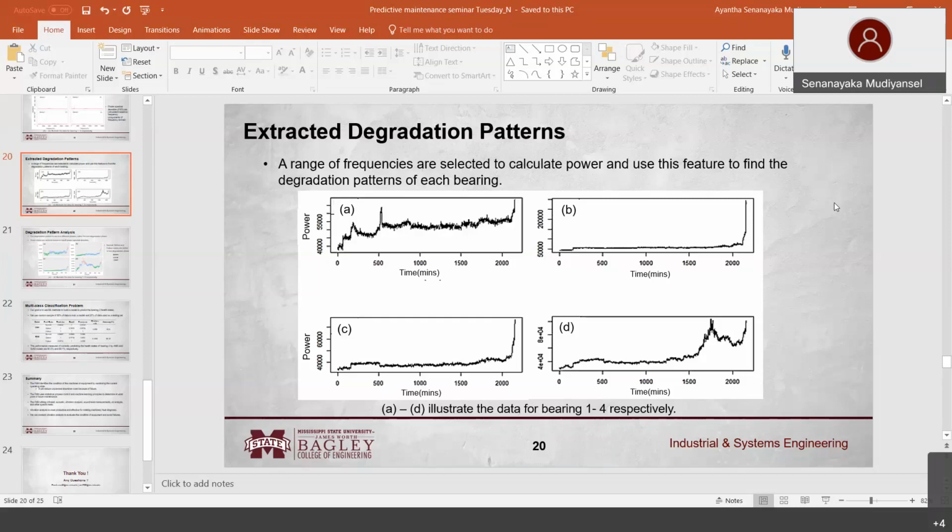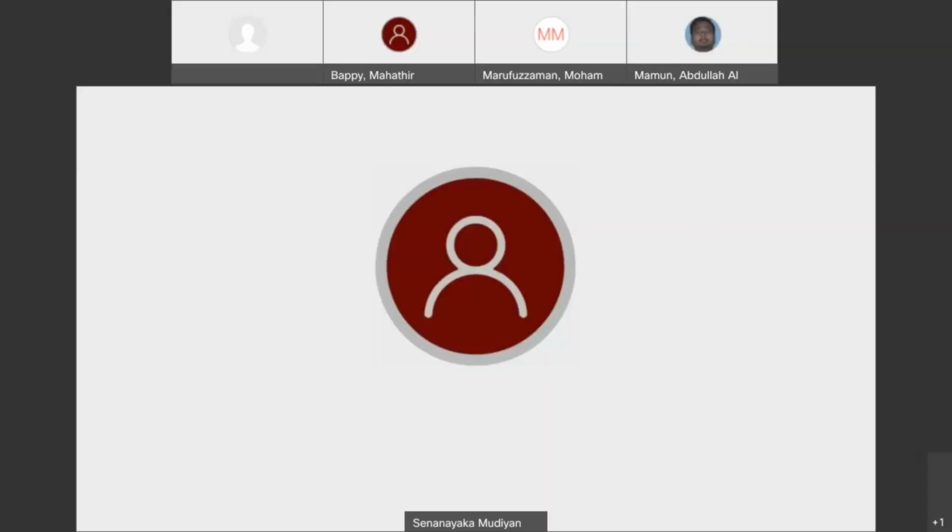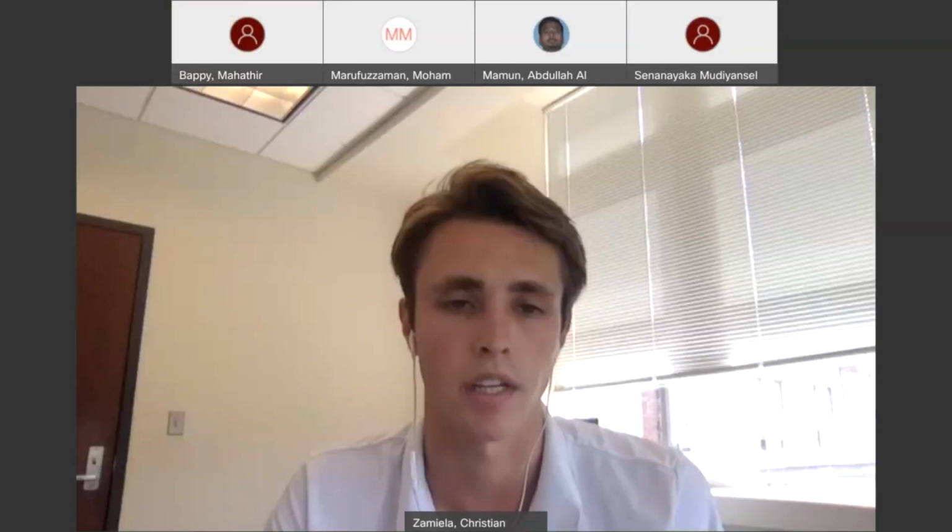So that makes sense. If you have a faulty bearing, you put it in the machine, run it and capture that signal, and you run that multiple times with multiple different sensors to collect that data. Then that's your baseline for a faulty bearing. And then you'll run a normal bearing and capture that vibrational signal as well, right?